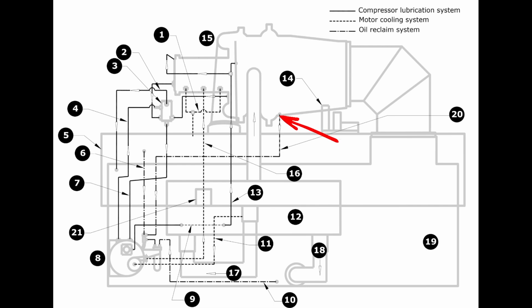In this particular example, we've also got a line, so if we trace this up, right there, coming across and up, right here at our nose cone, or the suction inlet bell of the compressor, we've got a tap right here at the bottom. The reason this is here is so that if for any reason any oil makes it up the suction line, it'll hit our guide vanes in here and hopefully collect down here at the bottom of the nose before it's able to make it into the impellers. That is our best case scenario.